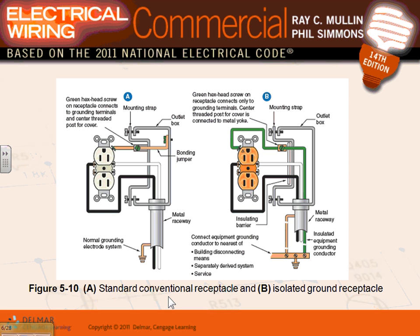Now, in our project, here's your issue. In our project, guys, we're having underground PVC conduits. If we're in underground PVC conduits, what are you going to use? You're going to need two grounds, one clean, one dirty. So in this case, you're going to end up pulling two isolated grounds for the receptacles. One will be green, used for the clean, for the receptacle, and the other one will be used to ground